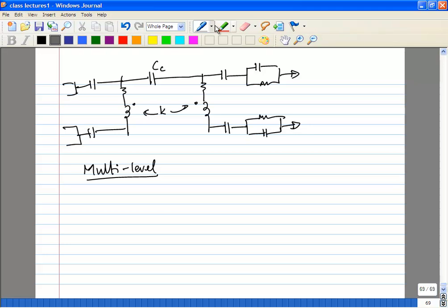From the biasing supply. Exactly. If you take power amplifiers, you will often see circuits biased such that you have an inductor from VDD to the transistor. So for example, you could see something like this. And let's say you have some resonant circuit, matching circuit, whatever, and this is your load resistance. You could perfectly well have a case where you're really not interested in the Q of this inductor because you're not using it as a resonant circuit.